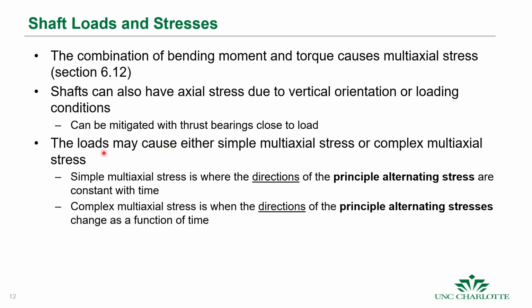Just as we saw before, we can classify multi-axial stress as either simple multi-axial stress or complex multi-axial stress. Recall that simple multi-axial stress is where the directions of the principal alternating stresses are constant with time.